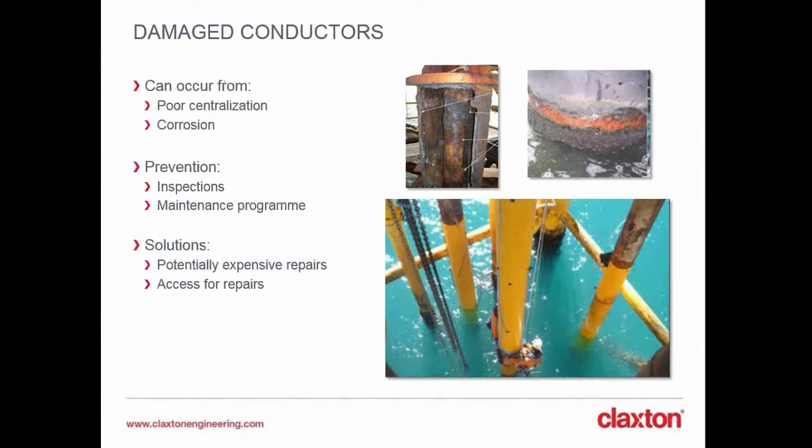As well as the guides, you can also, of course, have problems with your conductors. You can also get damage on the conductors due to excessive impact with the guides and the effect of corrosion over time. The two pictures above show a couple of examples, quite extreme. On the left-hand side is one at the cellar deck level, and the other one shows a picture around the splash zone level. But those are just typical examples of potential damage or corrosion that you could have on your conductor.